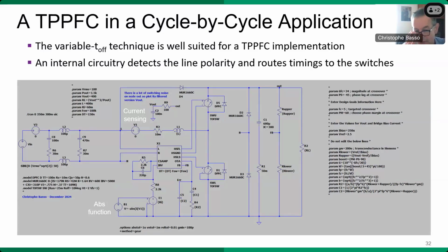I've used that technique to build TP PFC, totem pole PFC. So you can see the fast leg, which is here. When I run simulation, I always start with a very basic and very simple circuit with perfect components, of course. And when it starts working, when I'm happy with the results, I will then replace these with a proper driver, bootstrap perhaps, MOSFET transistors and everything, so that I know my structure operates correctly. And if I drop in a component and suddenly it doesn't work anymore, I know that this part that I've added is the culprit of non-convergence.